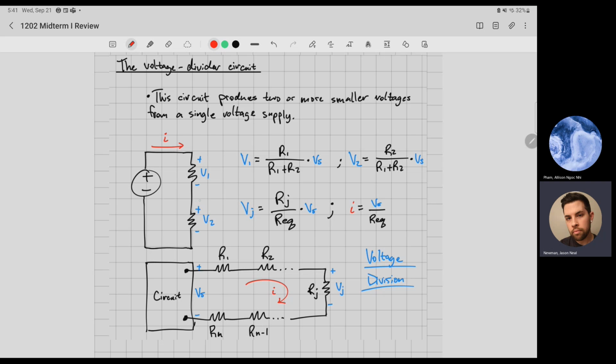That's really all it is, because if you say this is 10 volts, or no, let's say this is 20 volts, right? That means that the positive side of this resistor is also 20 volts. But in here, you're going to have something that's less than 20 volts. We don't know how much yet, but it will be less than 20 volts because you're doing a voltage drop across that resistor. And then this is ground, so this one will be 0 volts.